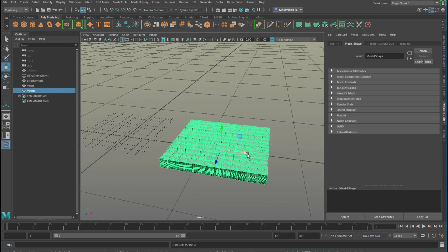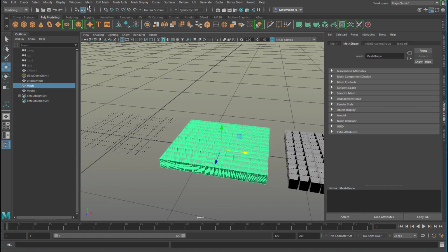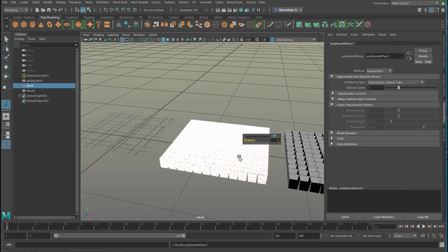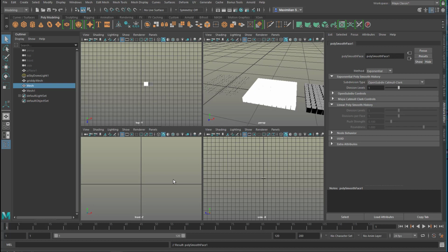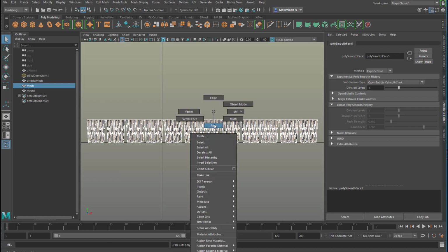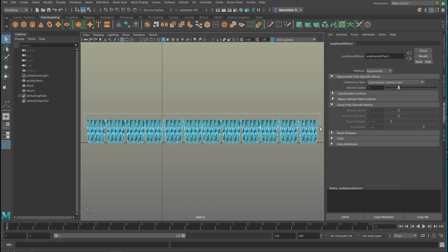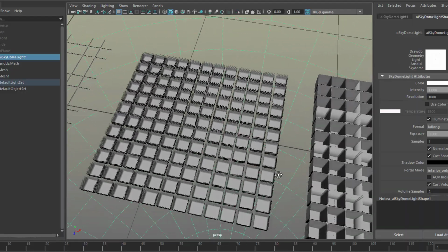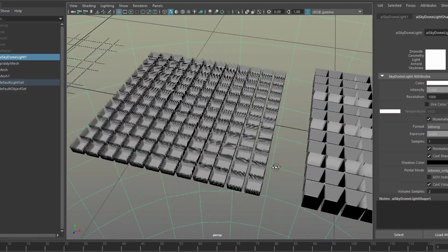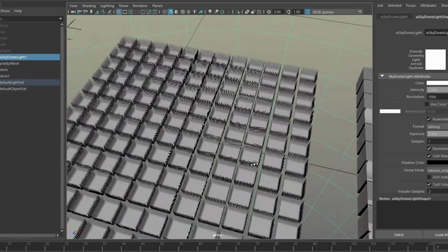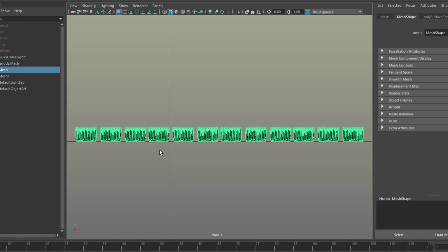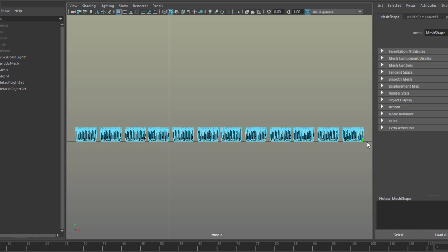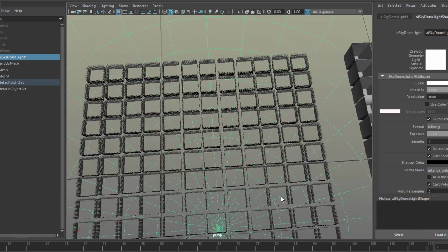Now let's duplicate this one and move it to the side, and we work on this one. Let us create more geometry, even more. Go to Mesh and smooth that object. So it's smoothed now, and we go to the front window again, and we press the right mouse button and use faces, and now we select the top faces here and we delete them. We have this arrangement now here, which is just cutting off edges from the top. Much more edgy, so to say. And we go back and delete more faces, namely the ones at the very, very bottom. So now we can look through them.